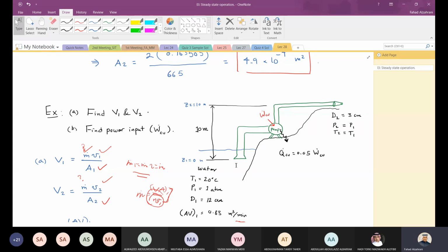Your reference is usually zero, which is the ground, or let's say the lower point in this case. This is Z1. My Z1 is the inlet, I can think of it as the level ground. Now I'm pushing this 10 meters higher up, so Z2 is plus 10. If this is taking it down, what will my Z2 be? Imagine Z1 here and the pump pulls the water and lowers it somewhere below.